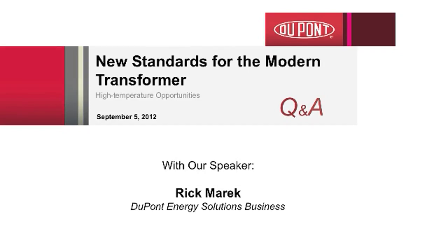A gentleman has asked us, the wire wrap you spoke about, is it a replacement to the normal kraft paper or thermally upgraded paper insulation for power transformers? I'm not sure. Say that again, please. Sure. The wire wrap you spoke about, is it a replacement to the normal kraft or thermally upgraded paper insulation for power transformers? Well, the wire wrap mentioned was actually Nomex, and it would be, yes, very different from the kraft and a higher temperature capability.